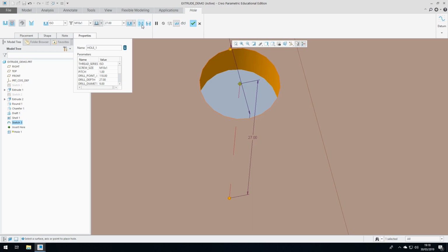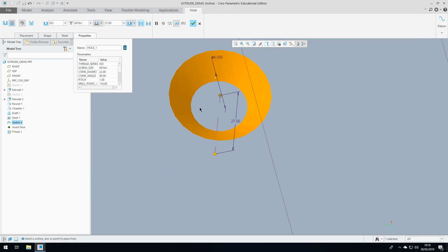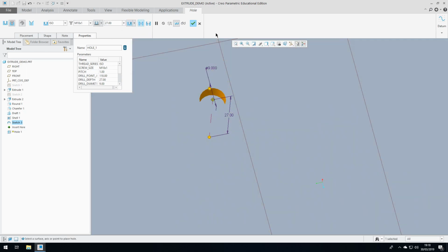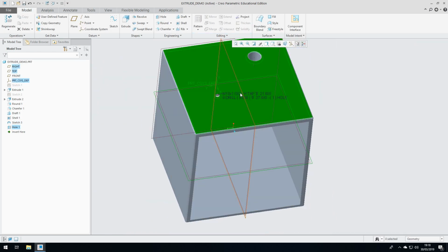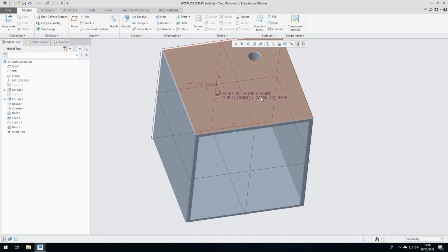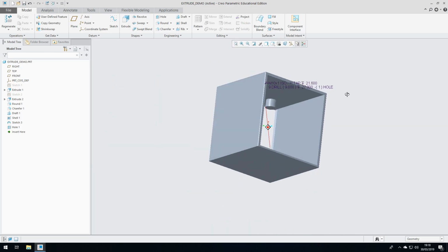You can also add countersinks and chamfers and things within this area. So for cap heads, if you want them sunk within, if this was a solid part, you use counterbore, and if you're using a countersunk screw, you obviously use countersink. You can set the values for those as well, like that. But again, we're just going to add a through hole in there. So this is called out within this, but it will also call out within the drawing as well if we went to make a drawing of this part.